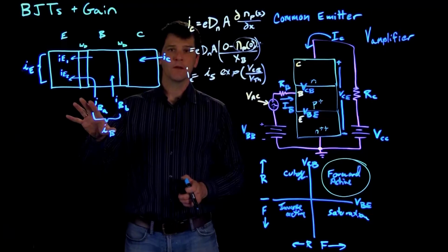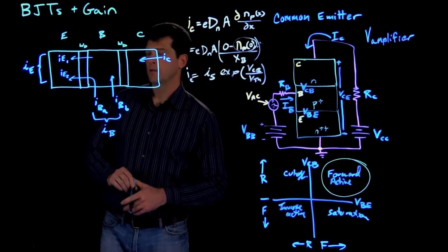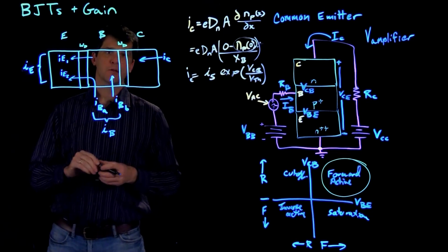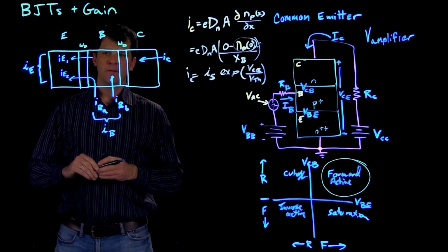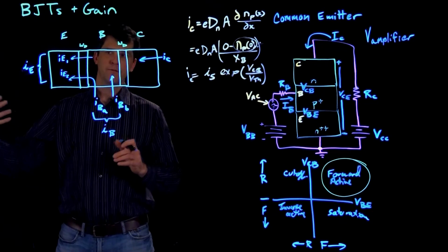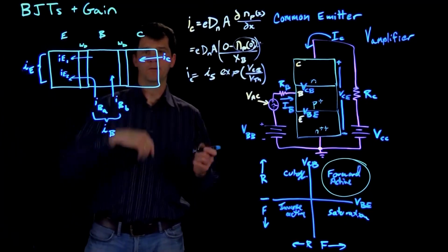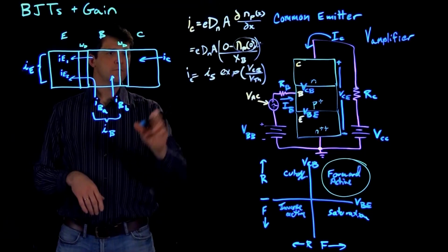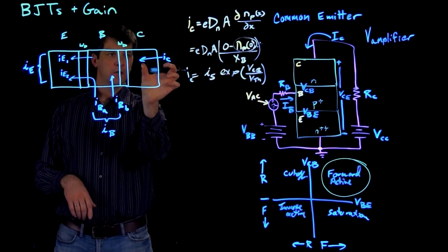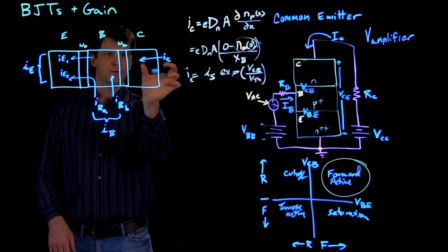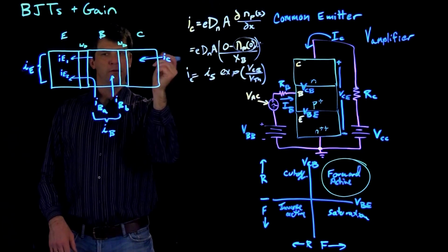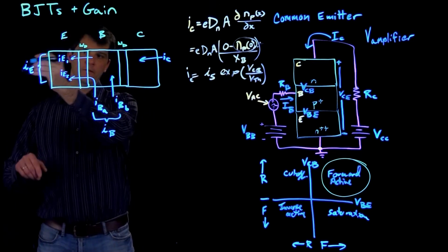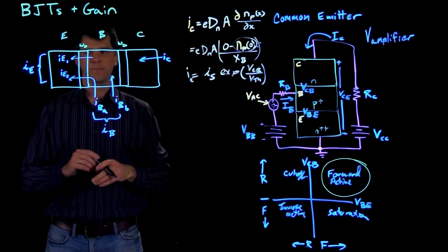Okay, so over on this side, I've redrawn the block diagram structure. And we're going to look at the flow of electrons from here to here, which of course produces currents going the opposite direction. So the collector current here, what we wanted to do is go all the way through the device unimpeded, and that's the same as the electrons making it all the way through.